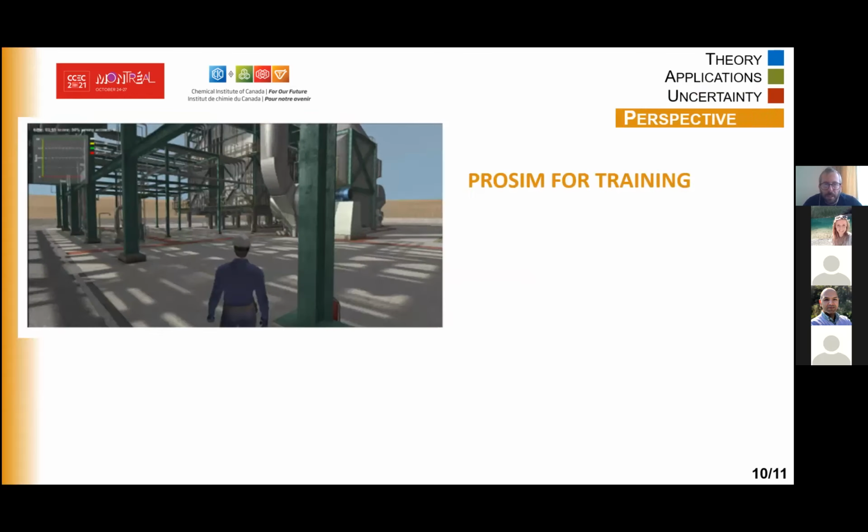So a little bit of perspective for process simulation. Process simulation is an interesting tool also for teachers and for teaching. Nowadays, and this is true, plant operators are trained in a virtual environment that simulates the overall plant. A dynamic simulation calculates the consequences of an operator action, or can generate process deviations to train the operator to react.